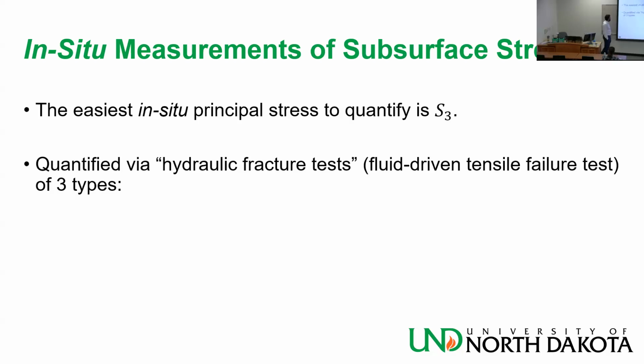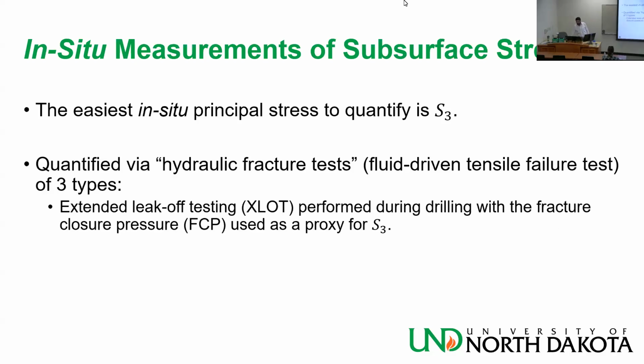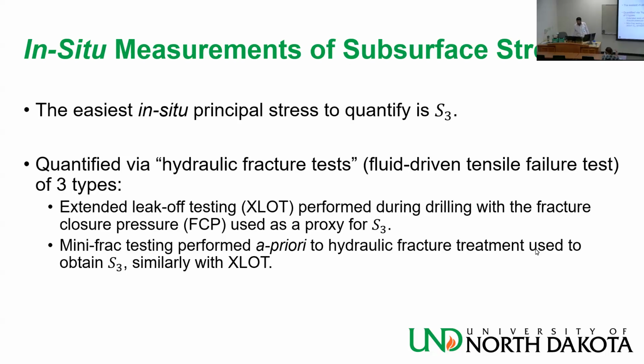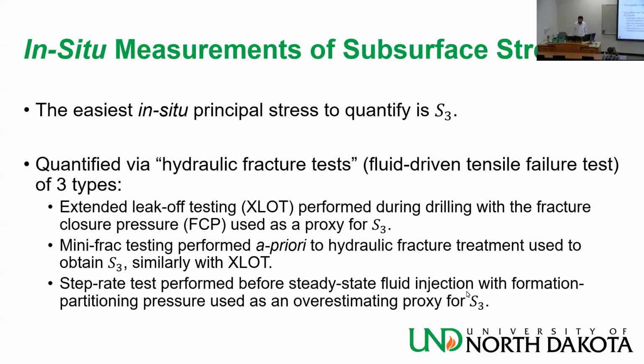What people call a hydraulic fracture test, maybe fluid-driven tensile failure test is a more technical name. Three of those are the extended leak-off, mini-frac, step rate test, a lot of variations of that. And also a lot of those are controlled by the state legislature. In Texas, you are mandated, if you are drilling an injection well, to run a, what do they call it, not a step-down test, a step rate test.